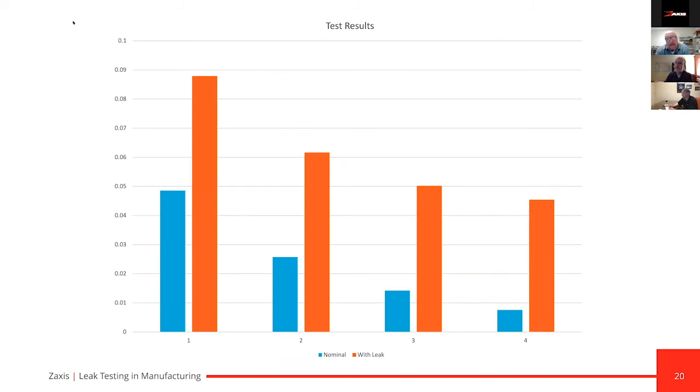I would recommend you would have more time in the fill step. The settle might only need to be 1 or 2 seconds long, just enough time for valves to close and any ringing that might occur because of an actual valve shutting and moving. There's not a real need to have a lot of settle time if you have enough fill time.